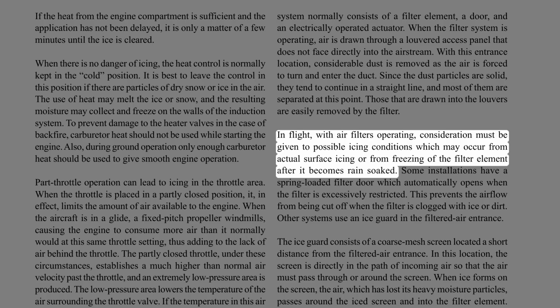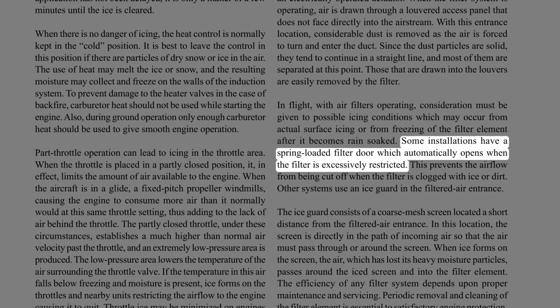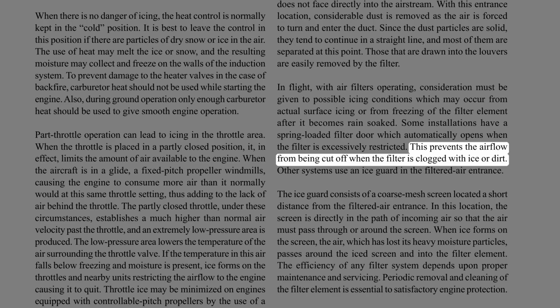In flight, with air filters operating, consideration must be given to possible icing conditions which may occur from actual surface icing or from freezing of the filter element after it becomes rain-soaked. Some installations have a spring-loaded filter door which automatically opens when the filter is excessively restricted. This prevents the airflow from being cut off when the filter is clogged with ice or dirt.